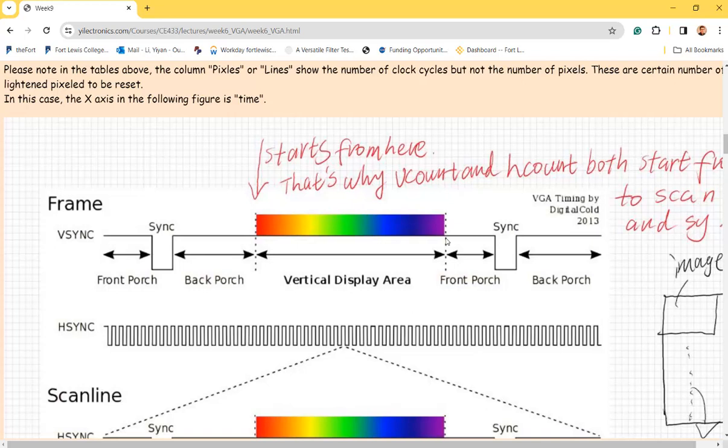I mean, more details? Could you provide more details? It's very close. So it allows the pixels to dim. If you have the visible area and then immediately followed by another frame, they're just too close to each other. It's probably not totally discharging all the caps for the pixels. So it gives you some time over here to discharge all the colors over there.